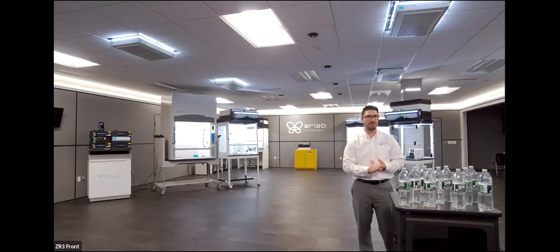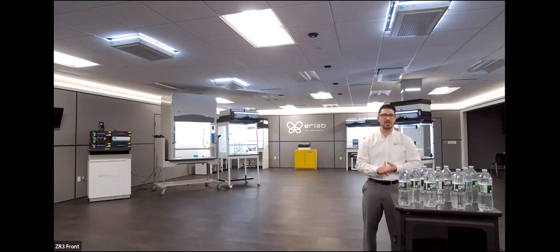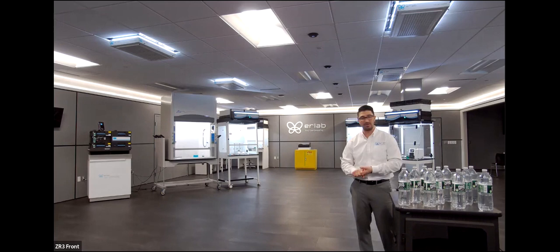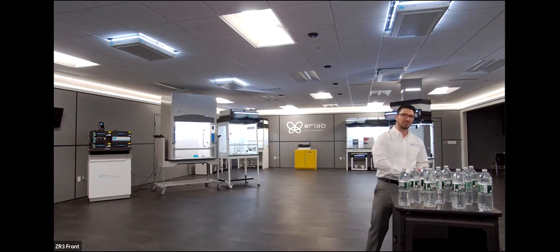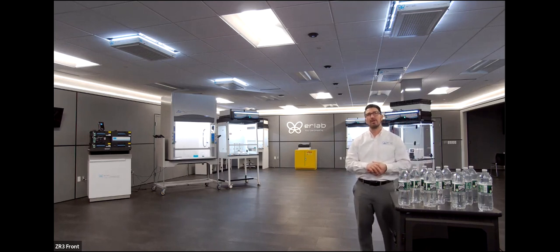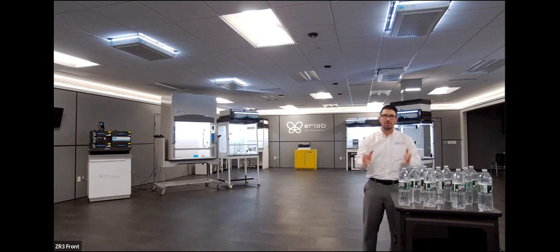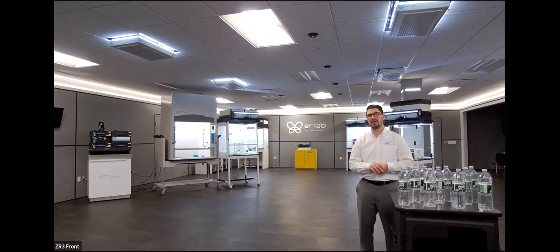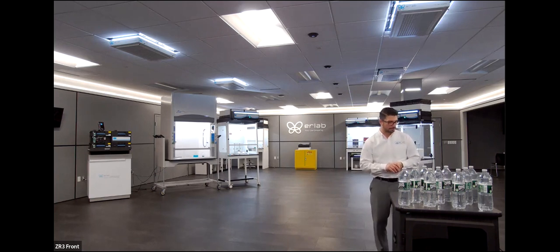Obviously the overall volume of space we're treating, and then we have to look at occupancy, load density factors, right? Is there a lot of people in that space? If there's a lot of people in that space, we're shedding. There's a lot of things that could possibly shed in regards to viruses, and we're just stirring up generated particles and pollution. So a lot of different factors we look at, but generally speaking, one every 10,000 cubic feet of space.